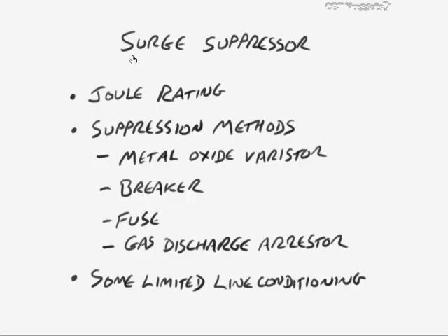Let's address also surge suppressors. Now, these are going to be very important. They can also be considered synonymous for our purposes with a surge protector, which I think is probably what most people call these. Although there's actually a bit of a difference, some technical differences, but for A+ exams, we can consider them the same. What these are going to do, though, is they're going to protect you against unexpected surges in electricity, which could blast through the power supply and, number one, blow out the power supply, or number two, could also pass through the power supply onto wherever you have power connected, the motherboard, your drives, whatever, and it could fry those items as well.